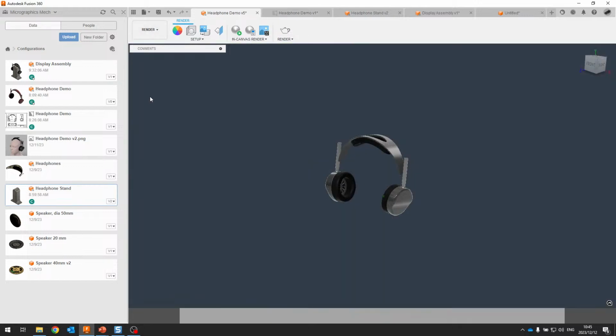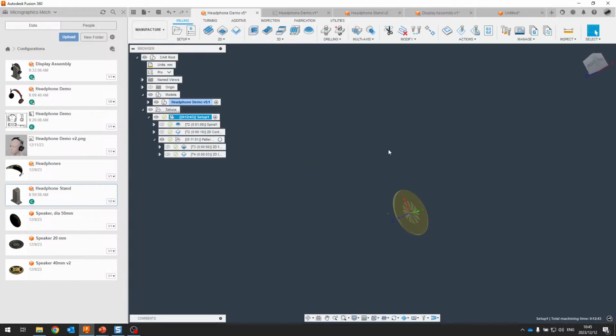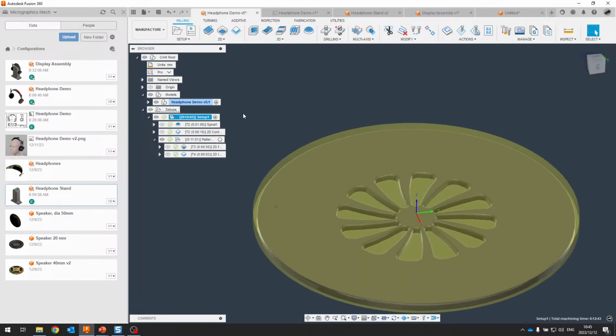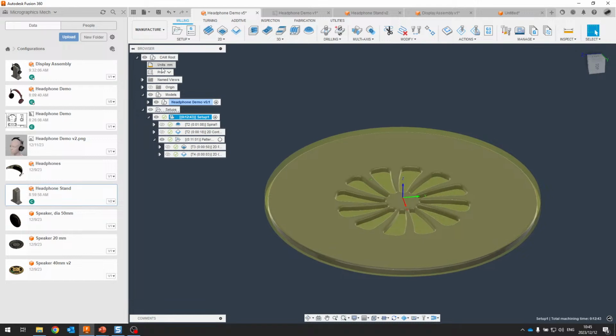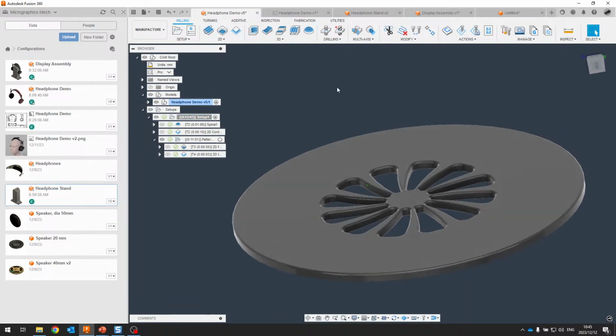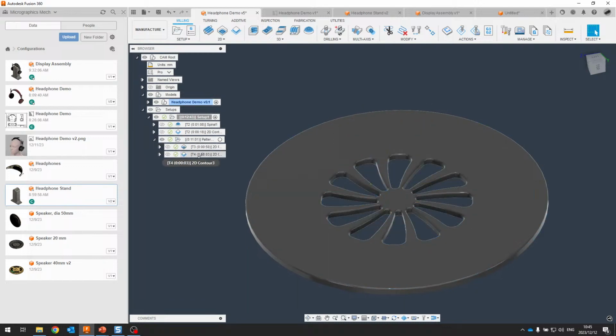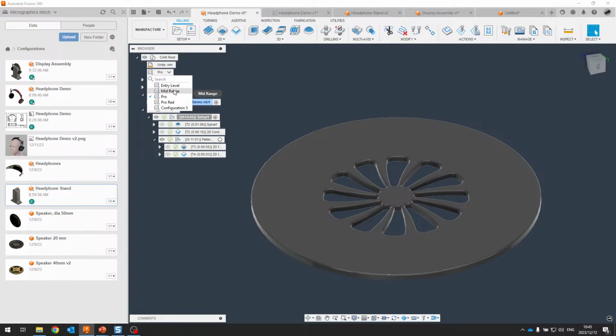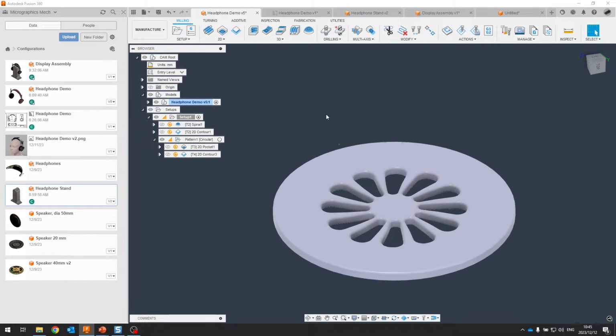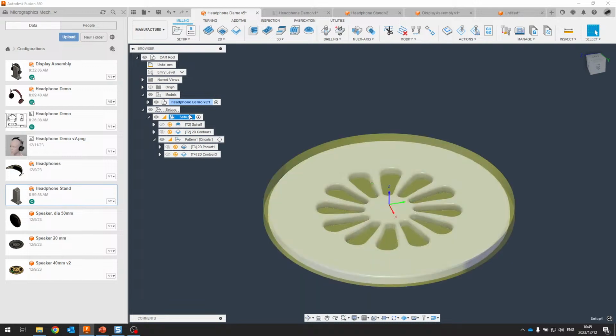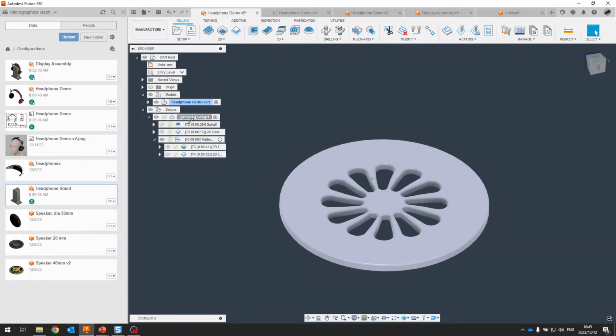And then lastly, if we just go to manufacture, just to show what that looks like, I've isolated a single component here. This is the Pro model speaker mounting plate. It's very basic geometry here. We've got a couple of toolpaths. If we change from Pro to, let's say, the entry level, which was a smaller speaker, the geometry will update. We can see that it's much smaller. With the toolpaths, we can quite quickly regenerate them, and they are now regenerated for the smaller geometry.